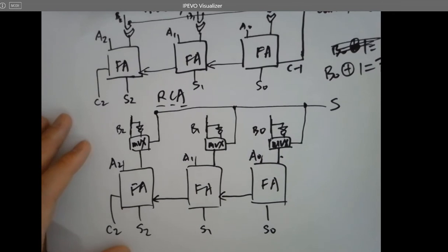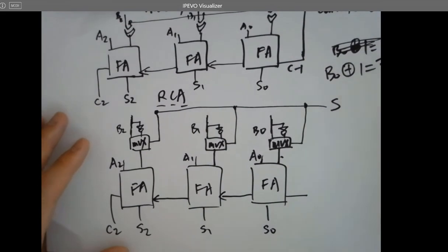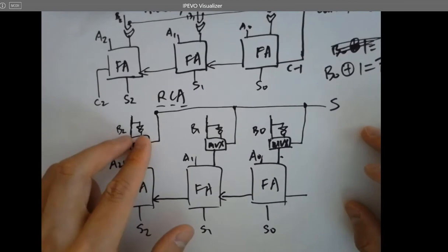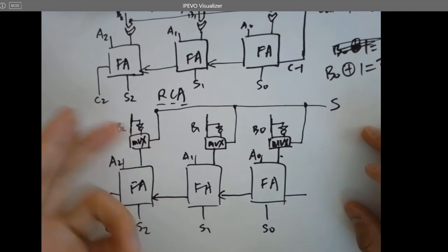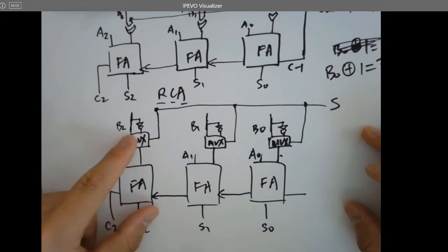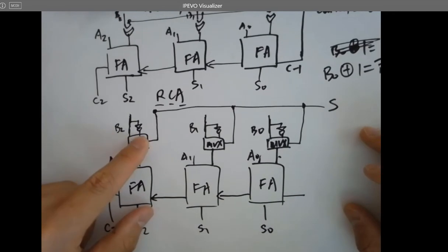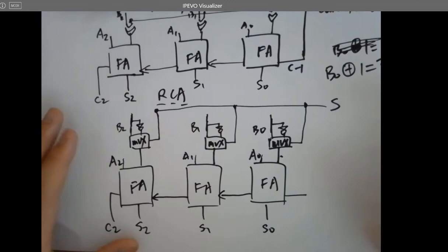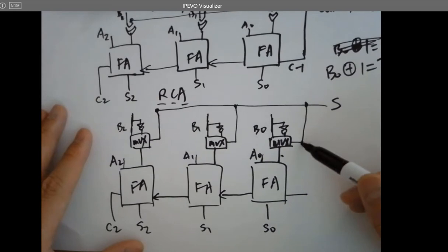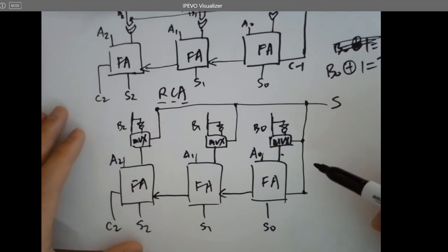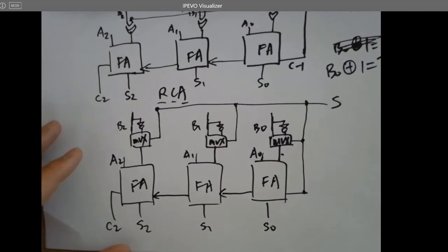And let me know what else I need to connect in this circuit. So I don't have this, right? Do I want to invert S or directly short S to here? Depends on how you want to design, right? Since these two inputs are exchangeable, there are two inputs, you can assign this one to B naught and this one to B, or this one as B, this one as B naught, doesn't matter. Depends on the circuit. If you do not have to invert S, if you can directly short S to here, which is the best, since you are saving space, you're not adding an extra inverter.